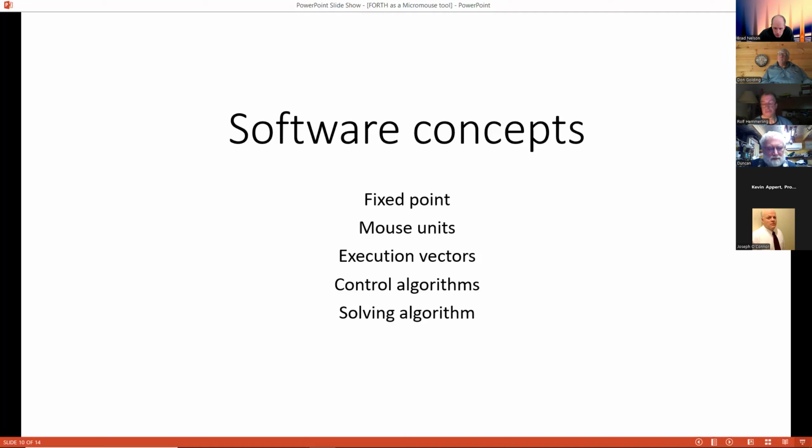The control algorithms are simple PD controllers, that's proportional differential. There's no integral term. The I term normally takes out systematic errors, such as different wheel diameters, that kind of thing. It's much better to build the thing properly in the first place, and it also gives a faster response.